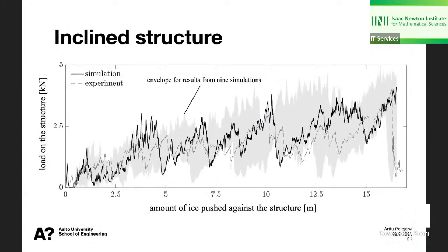Here are some results. Now it shows a little bit badly but anyways. What I've done on this slide is compare the horizontal load on that structure from my simulations and from my experiment. And what I see is that they show very similar behavior, basically. What you don't see is that that's just one simulation, but I ran 9 simulations for this with different tessellations, different discrete element sizes, and so on. And they all seem to fall quite nicely on top of this experimental data, basically.